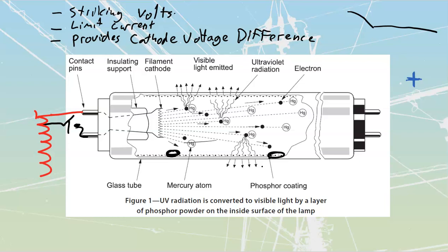Once that seasoning has happened, you're going to get much better light output as well. And that whole concept of the mercury dropping to the bottom also happens during operation, where you're going to have striations, it's called, which are lines across the bottom. Those striations are usually mercury that has fallen to the bottom.